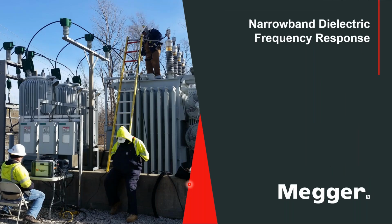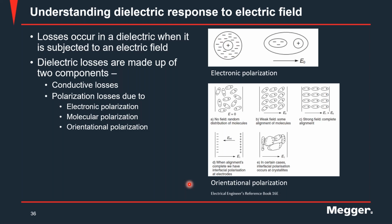So that was power factor testing. Let's now talk a little bit about variable frequency power factor testing. Before we get into that, let's try to understand what goes on when a dielectric is subjected to an electric field. When you apply voltage across an insulation, two types of losses occur.